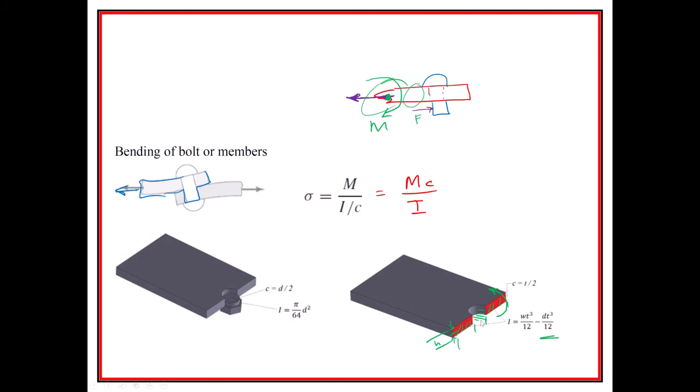This is a normal stress, so you would use the shear stress, shear strength, not shear strength, excuse me, the yield strength. Take that back. It's the yield strength because it's a normal stress. So every one of these is going to be a safety factor based on the strength and the stress that's appropriate for the situation. So that's going to be whatever the MC over I of this thing is. There's the strength over the stress.